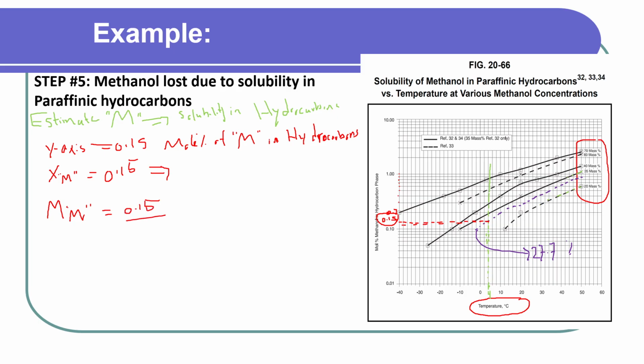0.15 divided by 100, which is 0.15%, multiplied by 881, where this 881 unit is kilomole per day of heavy hydrocarbons. So the 881 kilomole per day is the molar flow rate of heavy or liquid hydrocarbon on a daily basis.